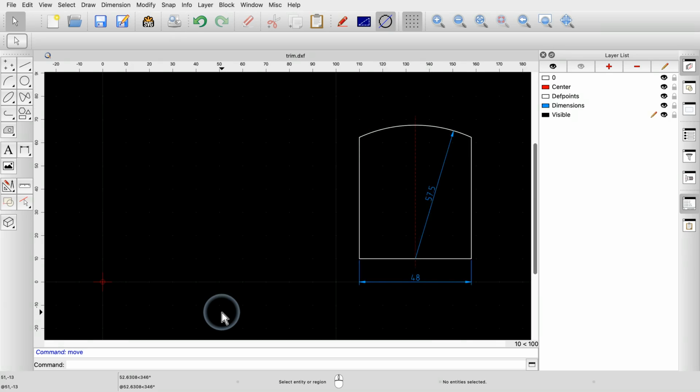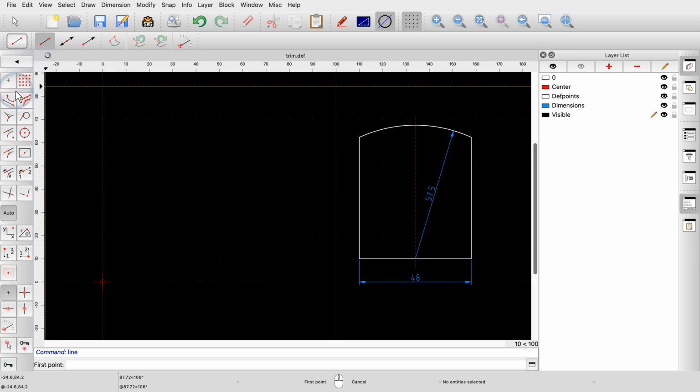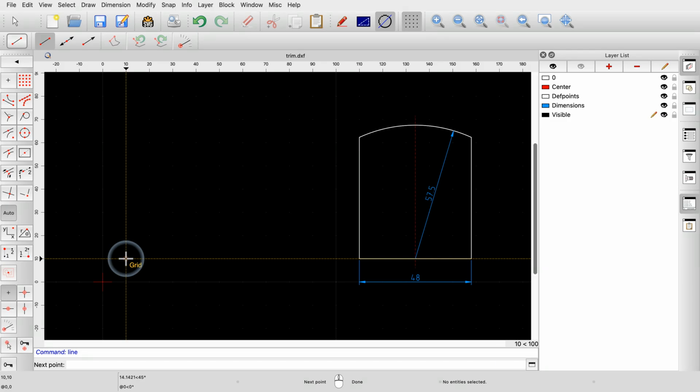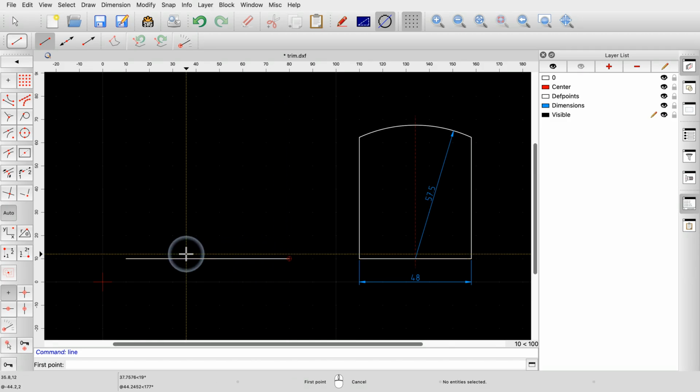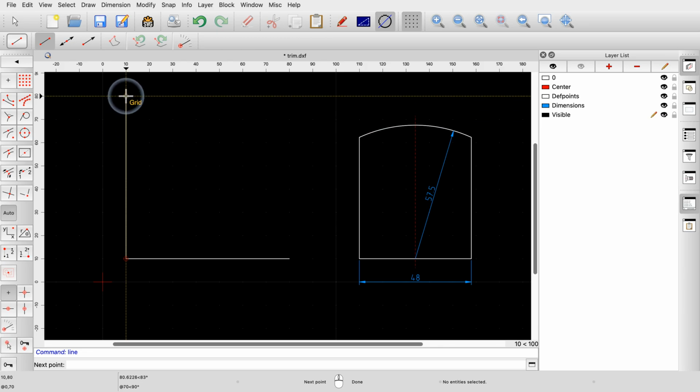There are also modification tools that do not require a selection. These tools let us click one or several entities to modify. In this example, we will recreate the drawing on the right. We start by drawing the 2 orthogonal lines that shape the bottom left corner. Although we could draw these to the right length, we choose to draw them deliberately too long using the grid. This is a technique that is often used in CAD to get the entities into the right place quickly without immediately worrying about their lengths.